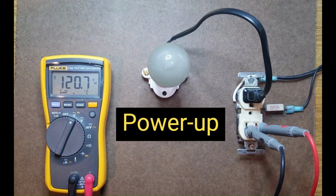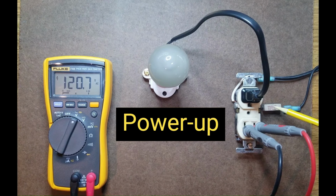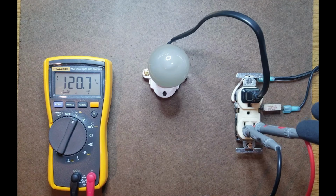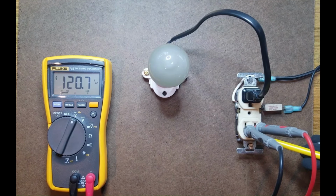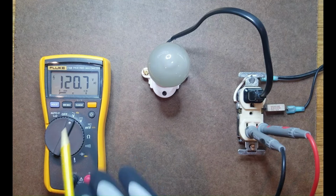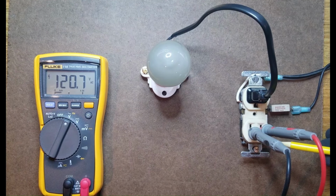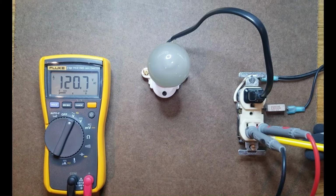And notice that even though we have a few thousand ohm resistance here in this loose connection, the meter is reading 120 volts. So if you were to go test this outlet with a regular voltmeter, because this is on traditional volt reading mode with a very high input resistance, you're going to read 120 volts and you're not going to know any better. You're not going to have any idea that this outlet is bad.